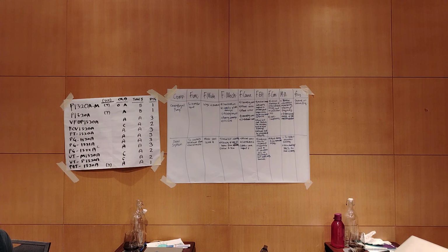Snoopy test? That is for leak, right? Leak test. You can also check using the temperature. To protect your seal, check temperature, and check whether the flush coming in is okay, pressure coming in. Draining also. Mechanical seal has a drain, right? So open the drain plug, then check for debris or so. For sampling, how frequent do you need to check the drain?